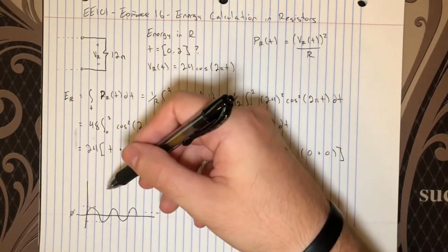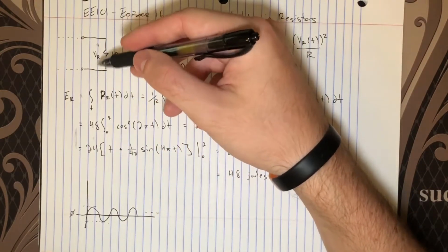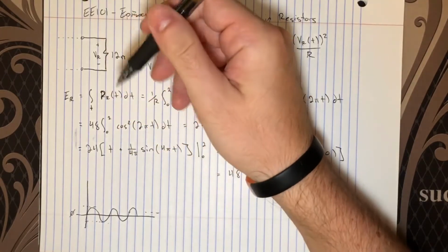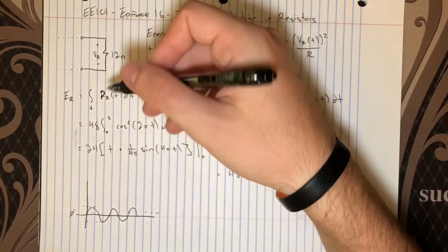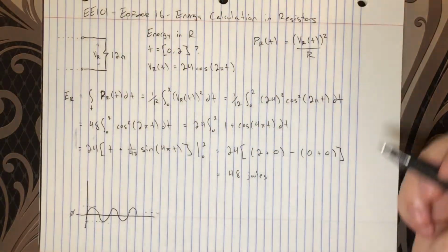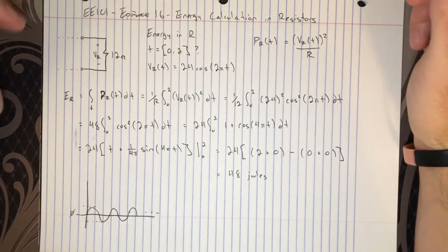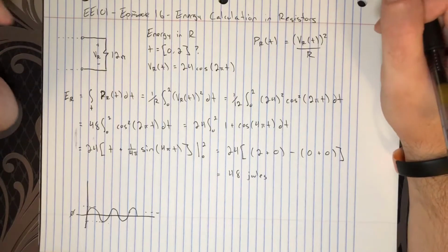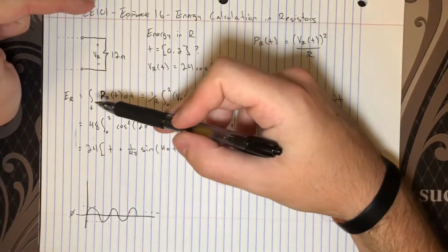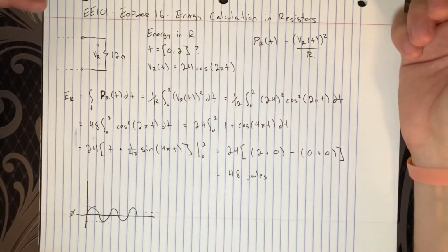Because all of a sudden we have negative V, positive V, negative V, and we know that depending on the polarity of this resistance, the current is going in a different direction. And that means that, if the current's changing direction, what does that do to our power calculation? What you need to realize is that this is just a resistor. It's a passive element. It can only consume power. So no matter what happens, no matter what direction this voltage polarity goes, it's consuming power.